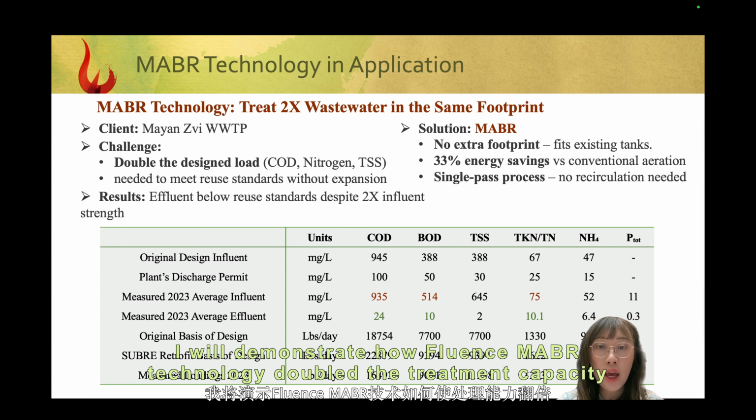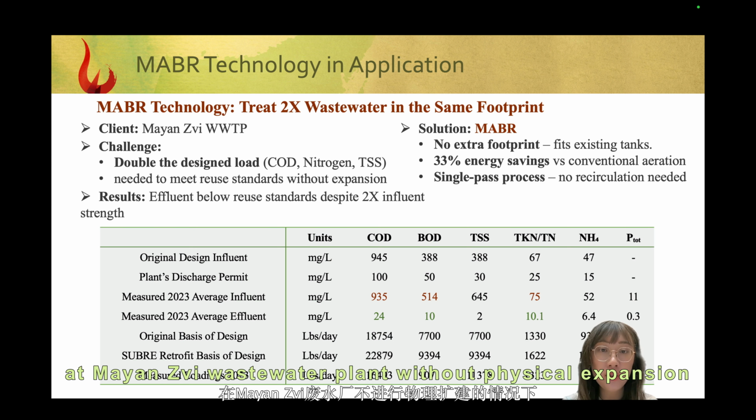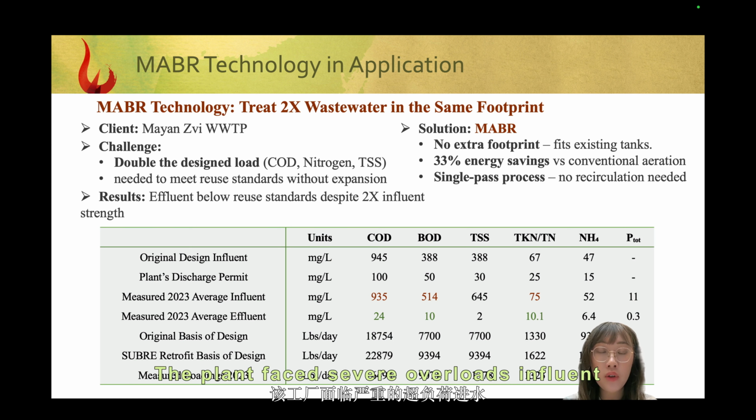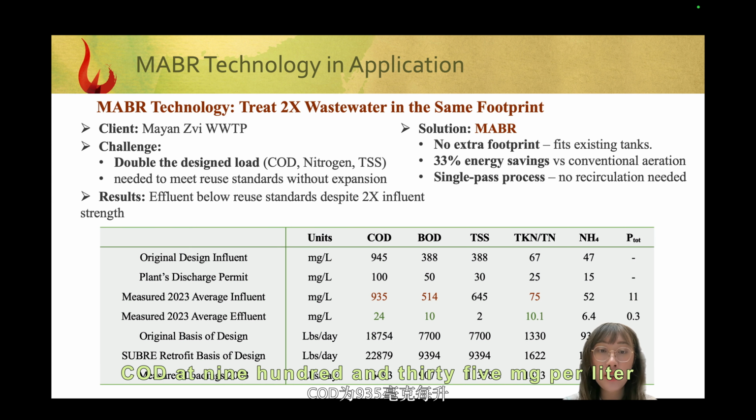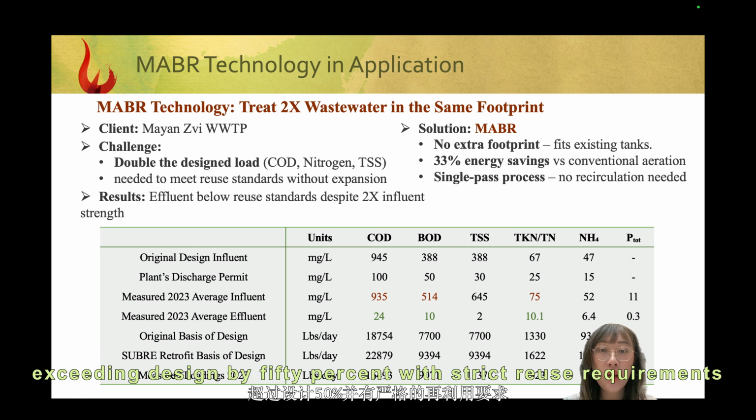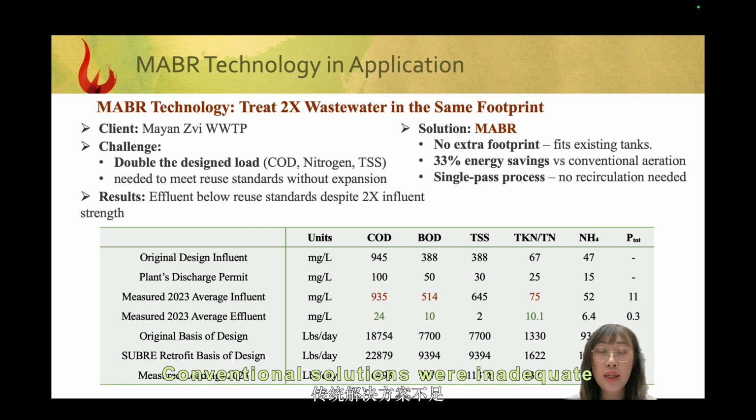I'll demonstrate how Bloom's MABR technology doubles the treatment capacity at my wastewater plant without physical expansion. The plant faces severe overloads. Effluent COD at 935 mg per liter and the TSS at 645 mg per liter, exceeding design by 50%, with strict reuse requirements. Conventional solutions were inadequate.